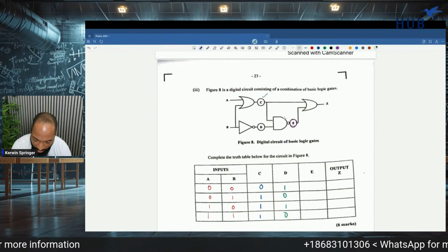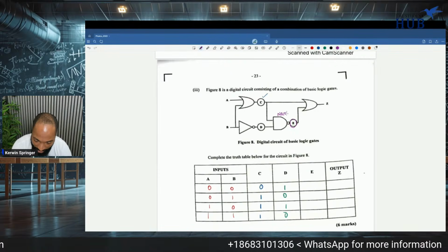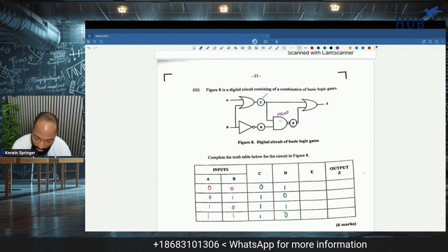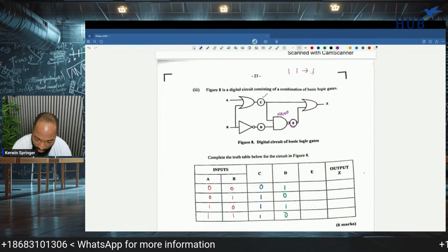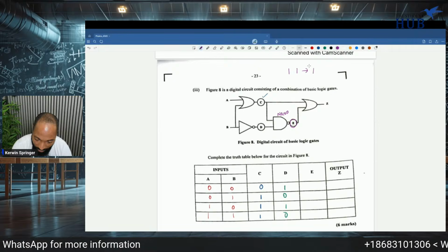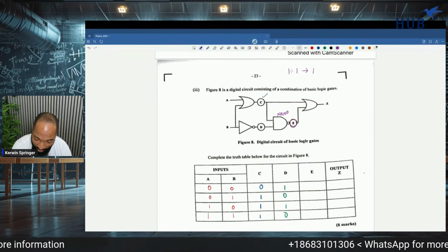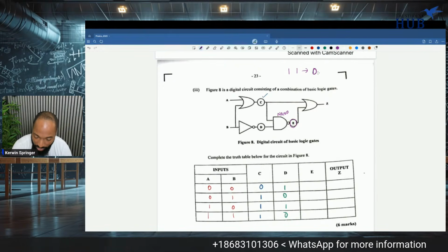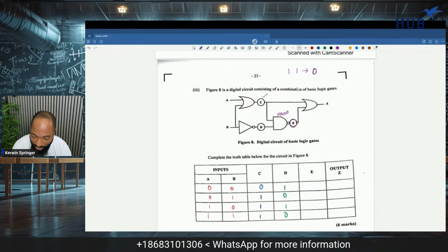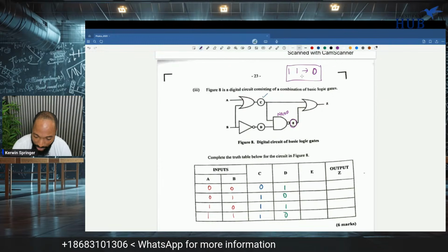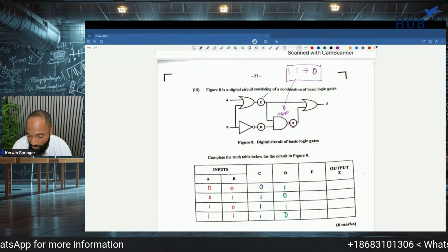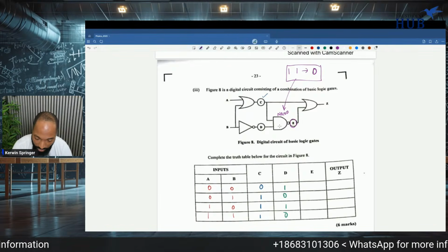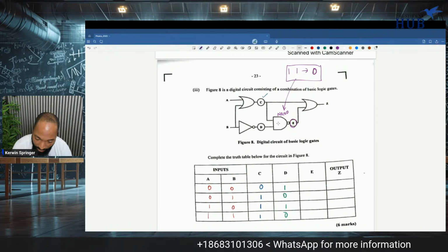So E, this is a NAND. And here's how you think about this. Remember, the AND gate only gives a 1 if you see two ones. So that means the NAND gate will only give a 0 if it sees two ones. Everything else will be ones. So this is the exception that we're looking for in the NAND gate. Once you see two ones, there'll be a 0. But everything else is 1. So great. That's your NAND gate.